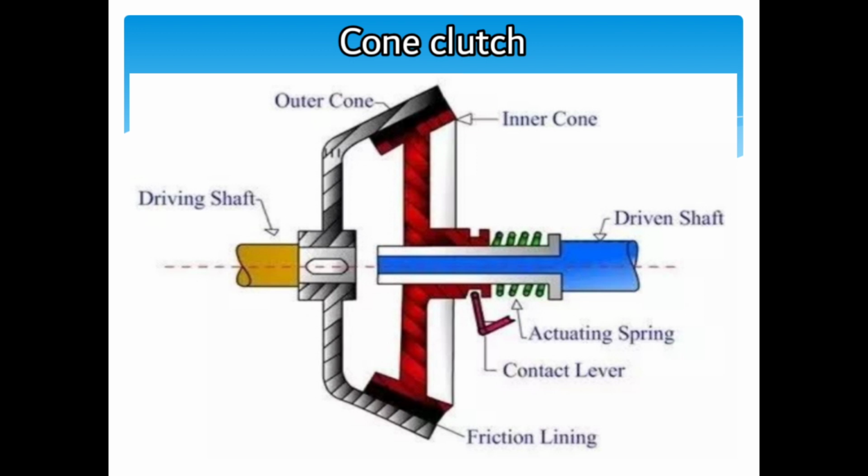The disadvantage with this type of clutch is that it only uses a pair of friction surfaces and the tendency to grab is very high. The small cone angle causes some reluctance in disengagement, and if the angle of the cone is smaller than 20 degrees, the male cone tends to bind or join in the female cone.